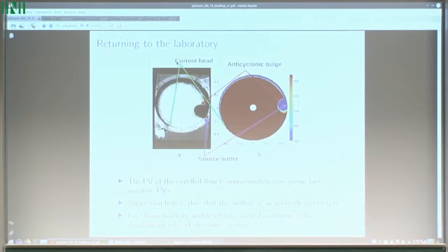We assume it's probably about zero total vorticity, so large negative relative vorticity in the experiments. And that's the case we just looked at. And that suggests that this outflow is an unsteady rarefaction, and that therefore the strength of this outflow is set actually by a critical control that we saw at the downstream edge of the blob.